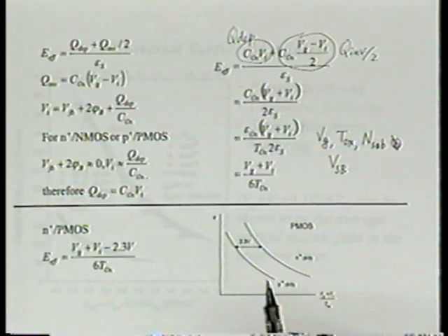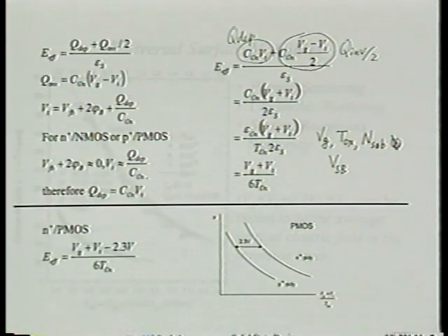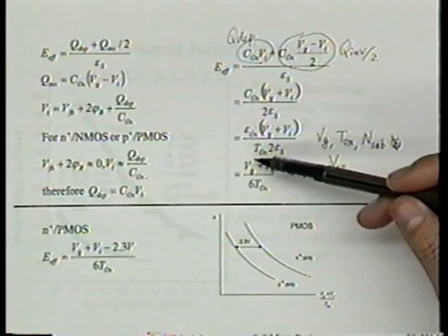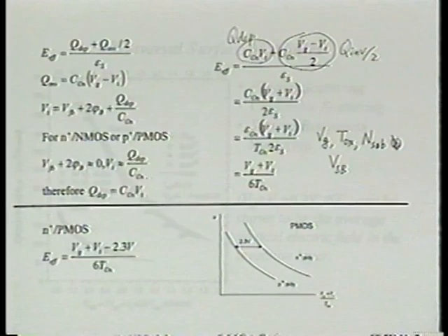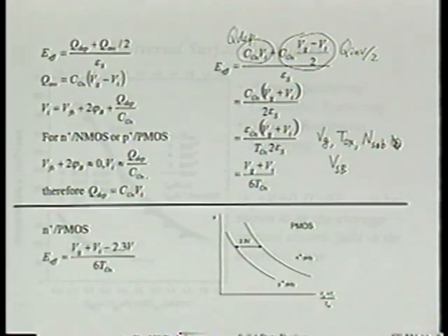I'll give you another example of why it's so important to know these facts. This is probably the only time you have seen VG plus VT. Everywhere else we see VG minus VT. Is that right? So it will not surprise you that very often when engineers try to optimize this device, they design the device slightly differently, maybe the implant dose changes, and so on.